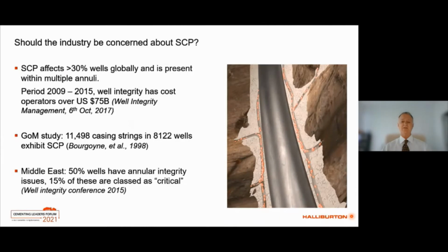However, the ultimate goal of well integrity is to prevent well control situations, uncontrolled release of hydrocarbons to surface. It all comes down to establishing what stops the sustained casing pressure affected wells from further barrier failure that leads to a well control situation. This is mostly about the integrity of the secondary barrier, such as the wellhead, containing the leak and the severity of the leak itself. Sustained casing pressure can affect more than 30% of all global oil and gas wells.